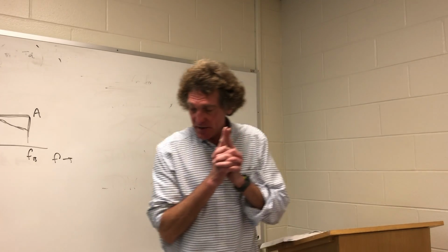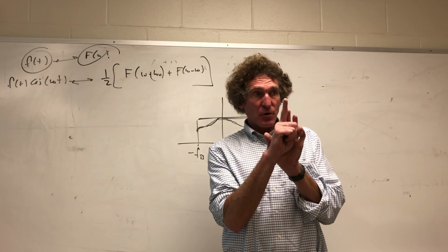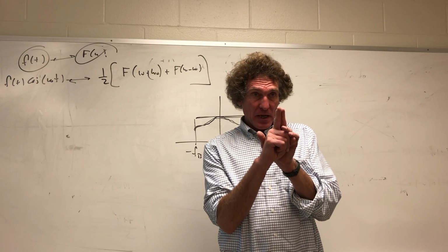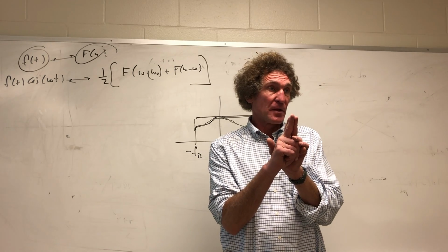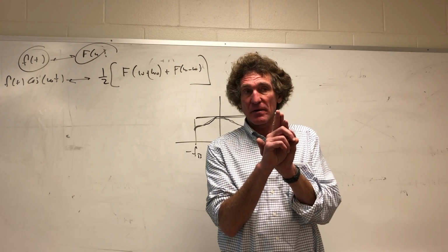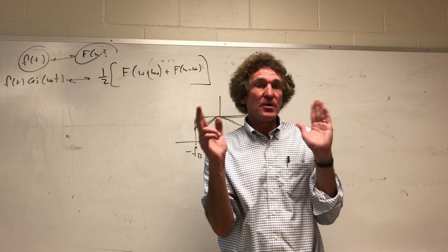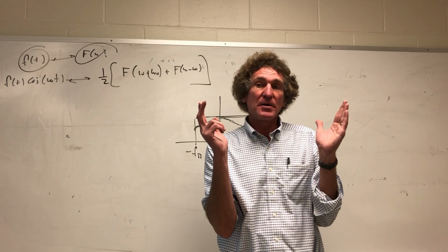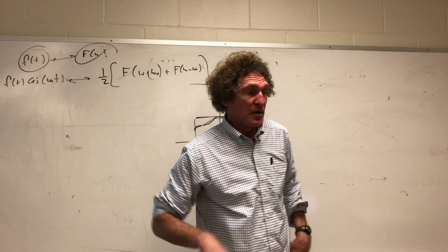By the way, you may not understand exactly what I'm saying, but when they talk about bandwidth, a lot of times they talk about percentage of the carrier. So when you're at 9 gigahertz, 10 gigahertz, if you have a 10% bandwidth, that would be 1 gigahertz. That's enormous. And if they want digital sampling and stuff, that would take an enormous bandwidth. That's the reason they bring it down to baseband. Normally at that frequency, you're only going plus or minus probably a couple hundred megahertz at most. You're not doing wideband.